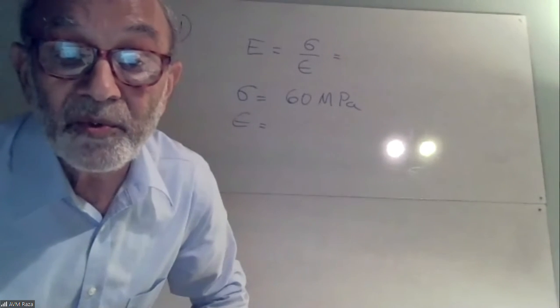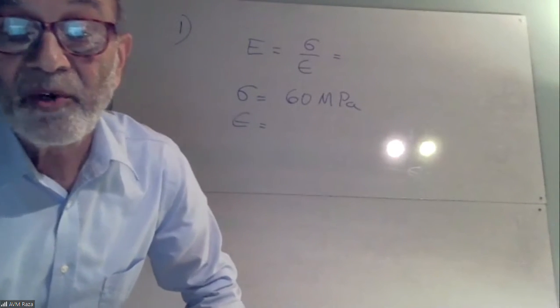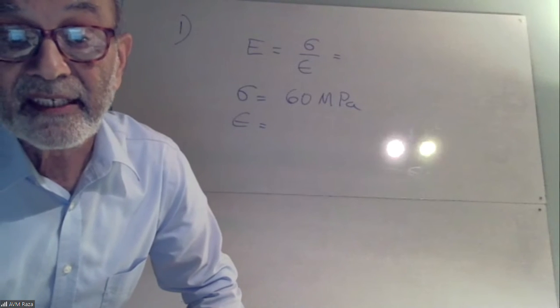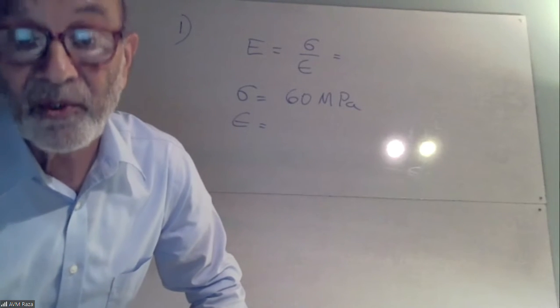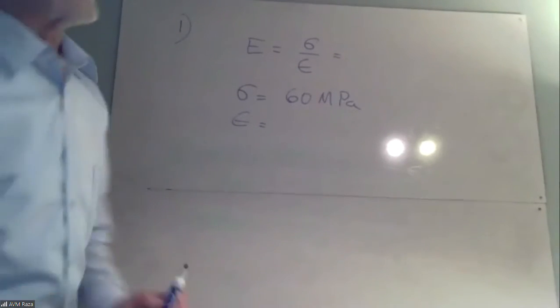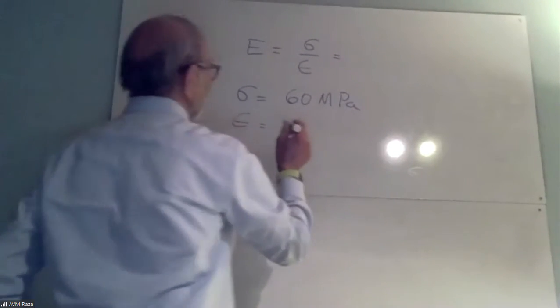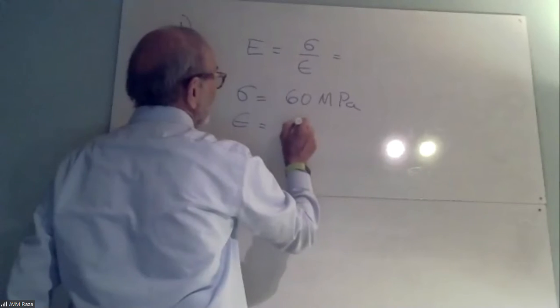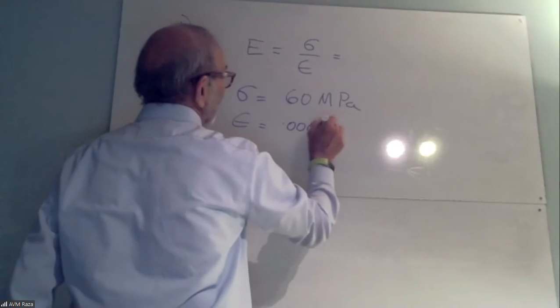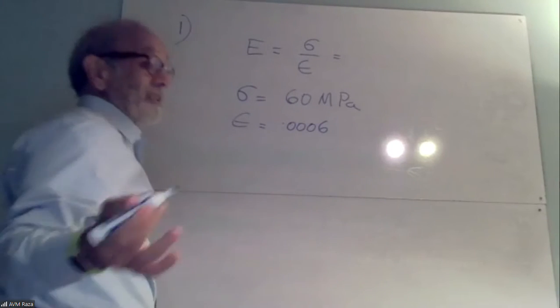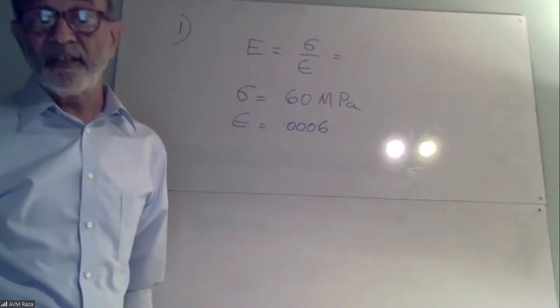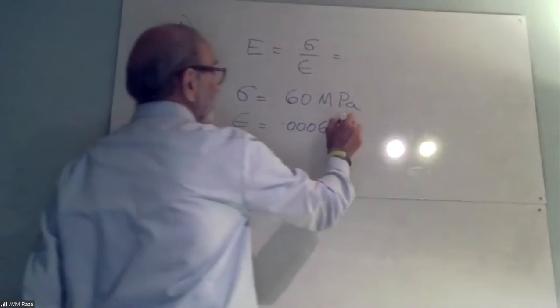Let's see, this is the line we are looking at. So this is 246, yeah, 0.006. One more zero. One more zero, 0.0006, you're right. So the strain value is 0.0006, and it doesn't have any units, but we can still write millimeters per millimeter.